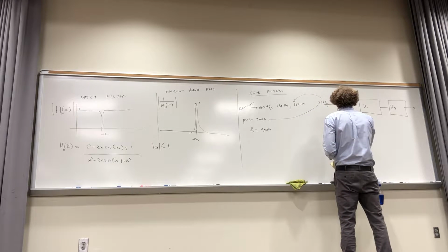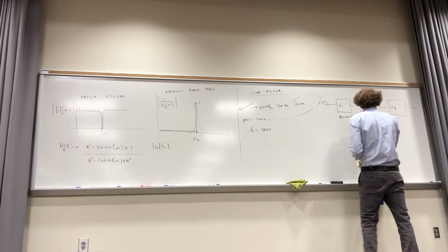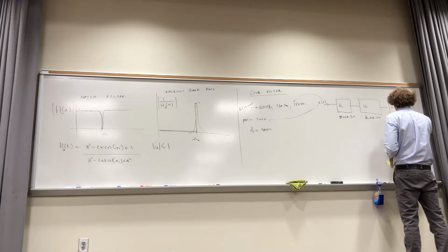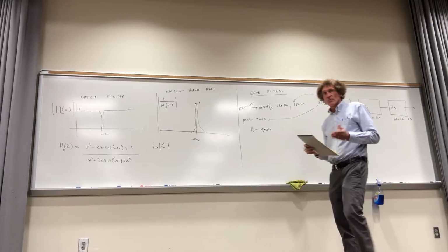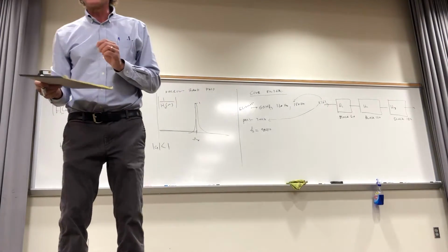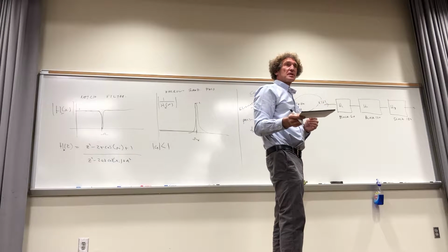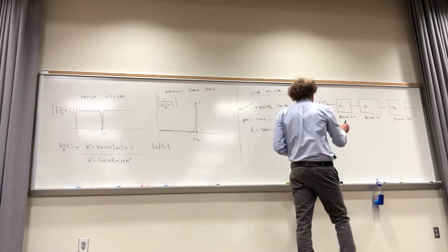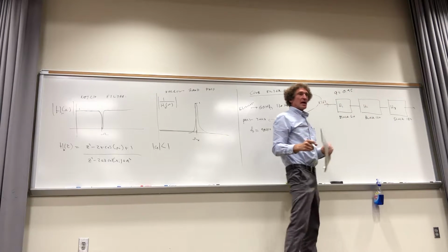So I could say H1 is going to block 60. H2 is going to block 120, and H3 is going to block 180. I'll only do one of these just to show you one frequency. It just repeats itself. Now, the value of A is something you're going to learn more about in your controls classes probably, and if you take DSP, digital signal processing, or digital image processing, you'll learn a lot more about filter selection, how to do it. But in general, you're going to make A about 0.95 or better, something like that.